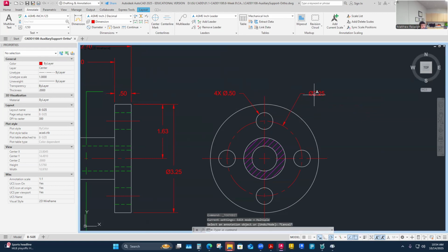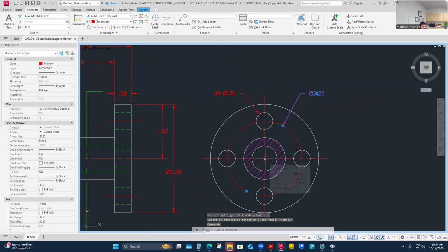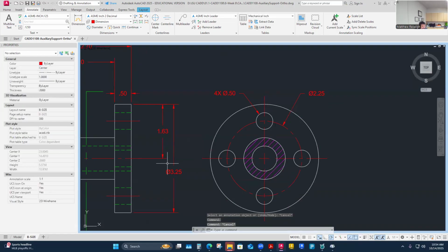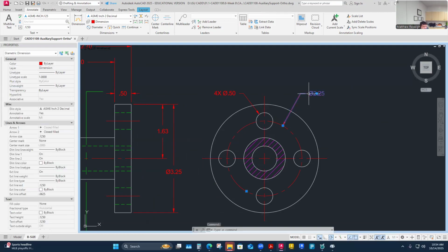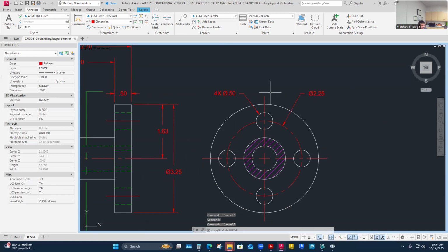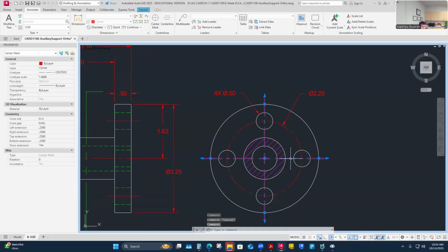And their location is now this, based off that same center axis, essentially. So it's based off of that from center. I don't need a rectangular, I don't need an X and Y because I'm just coming out from center to there. But what I need is an angular dimension, then how far apart they are. So this is like a single location for them. And they are shown to be on the center marks. So they're on the quadrants of that part, I guess.